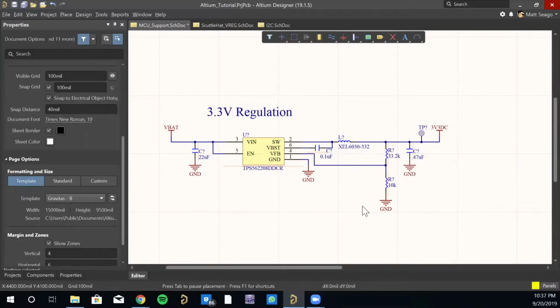Go look at the formula in the data sheet, punch your numbers in, and you should be able to get this resistor. Now, this does mean that when you're going to buy this resistor, rather than your typical 10%, 5% resistor, maybe you want something more like 1%. It depends on how important being super close to this value is, this 3.3 or whatever it is in your case.